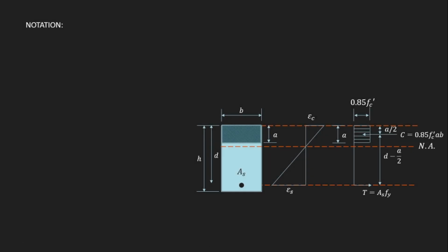We also have notations here in reinforced concrete. So what do these symbols and letters mean? The a is the depth of the rectangular compressive stress block. We have the actual stress, and when we convert it to the equivalent, we get a, where a is less than the value of c. The smaller c here is the depth of the neutral axis from the compression face. So this height. As you can see, our a is less than c.